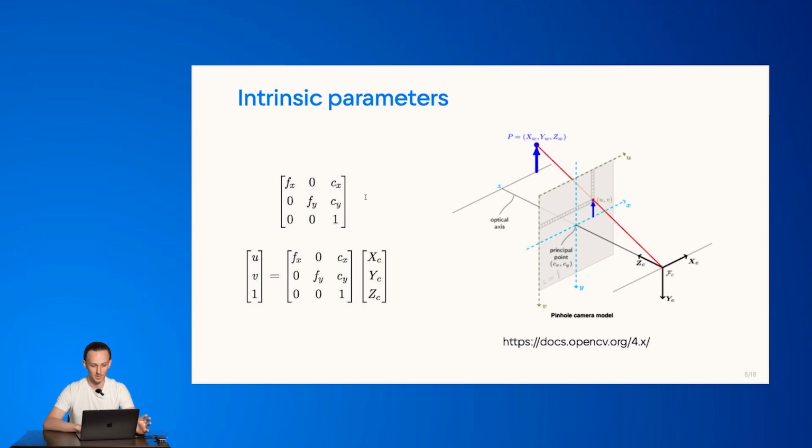If we imagine that we have all those 4 parameters already calculated, or we know them from the model of the camera somehow, we can perform the operation that is given at the left bottom of the slide over here. So this vector xc, yc, zc is the vector of 3-dimensional coordinates of the object in the camera frame.